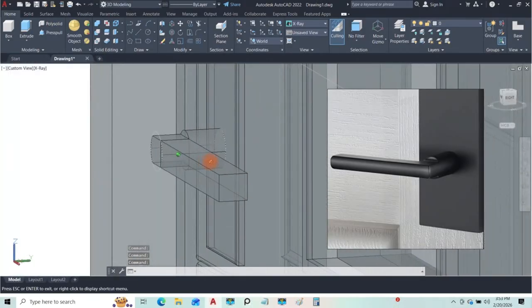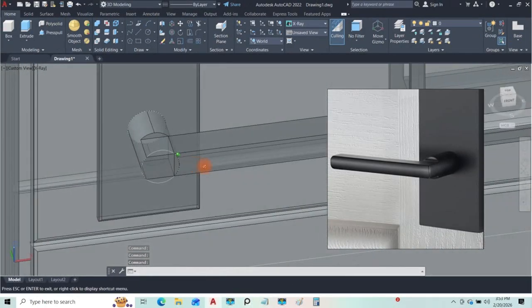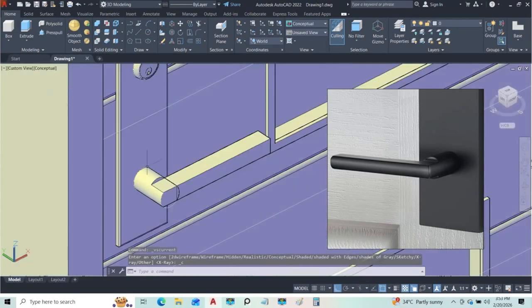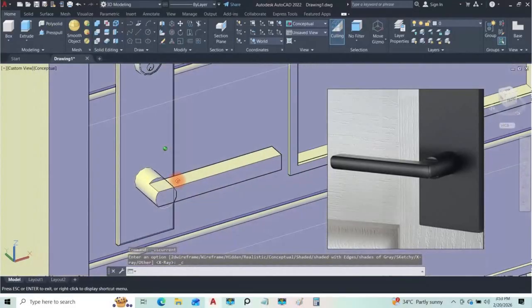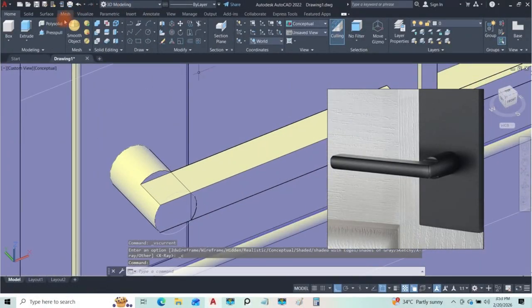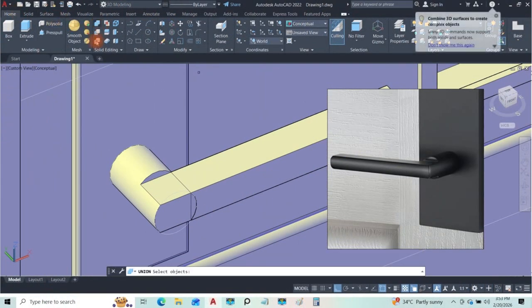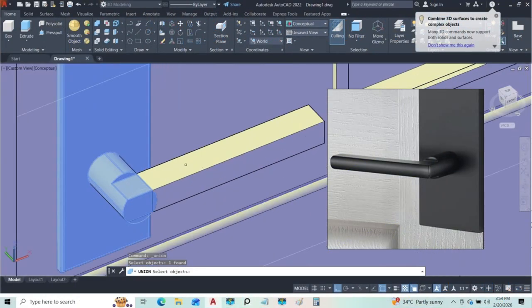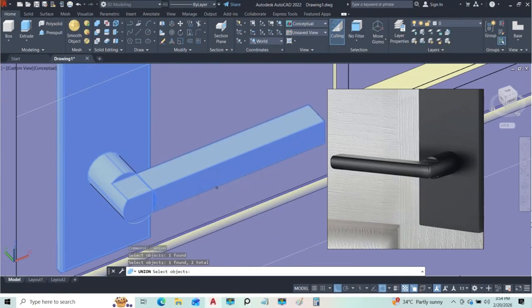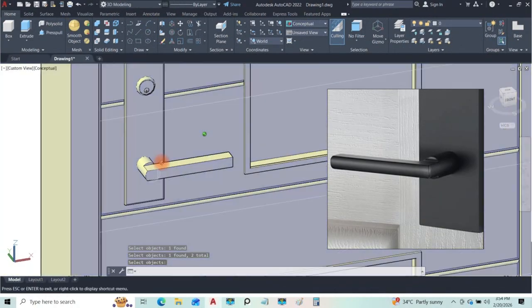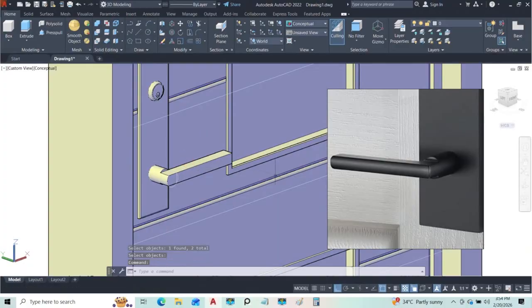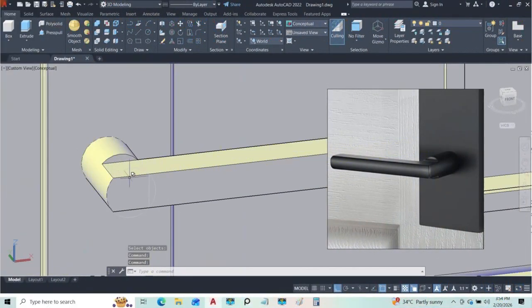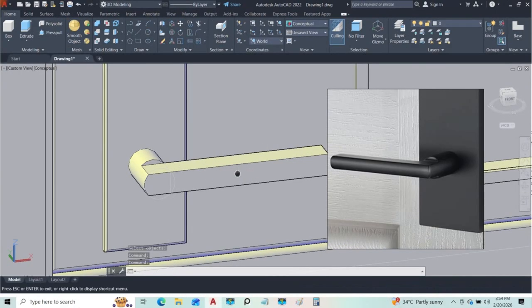All right. But before we smoothen this, let's join them together to becoming one object, and then we'll be able to smoothen together. See, this is what we have. So let's join this. We just select, go to union, select this, and select this, then press enter, and then we'll turn them to being one object. Okay, so this is one object. Then we can now round that up.